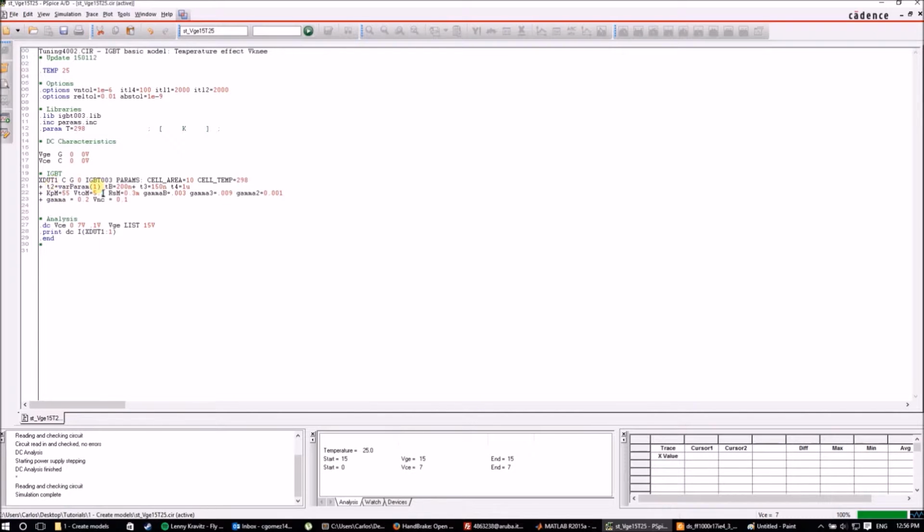You can assign any number to any parameter, it does not matter, but you have to always follow the same order. For example, in this simulation file I call T2 the first parameter by putting var_param(1). So later on, if I have another simulation where I also have T2, T2 has to be the first parameter. That's the only thing you have to follow.